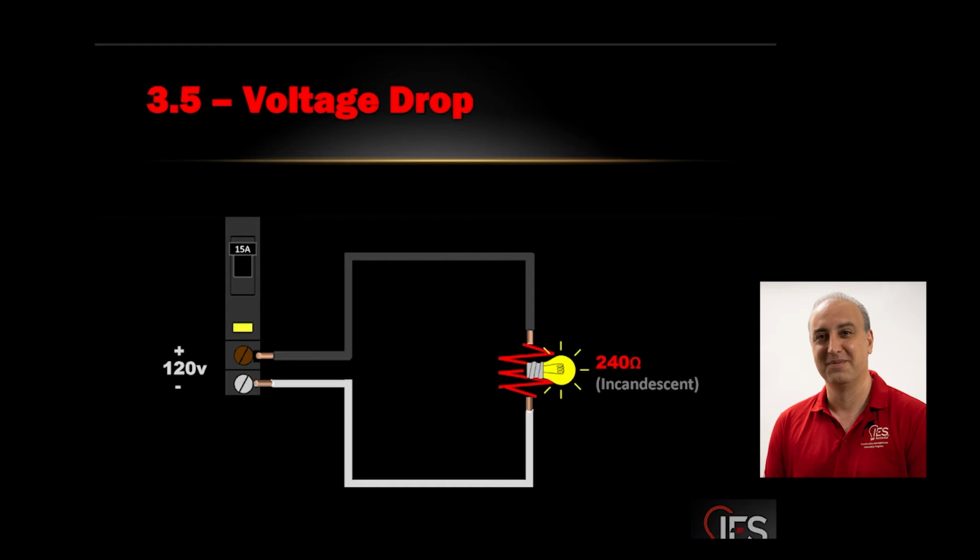That's a very good point, right? So let's say I take this out. This light bulb is out, right? Hot, everybody's scared of the black because you're like, oh, that's hot. Neutral, oh, it's connected to the ground at the service. That's not dangerous. Yes, it is. When this is out, if you put anything between this neutral and the ground, which includes your body, if you hold this and that switch is on, it delivers the exact same power as the other one. So even though we bring them together at the service, it doesn't mean they're doing the same thing. That's a good point.